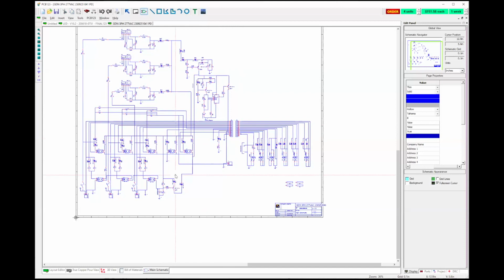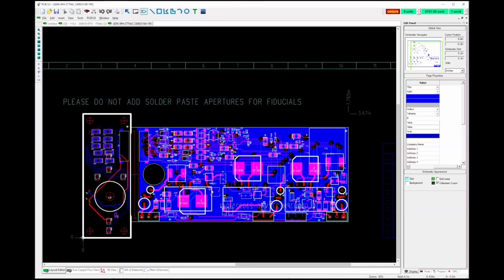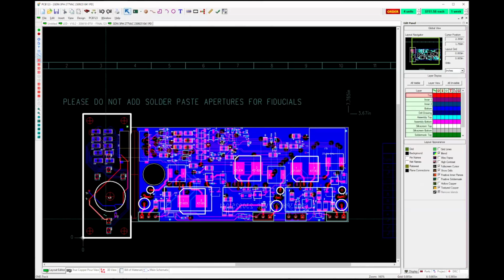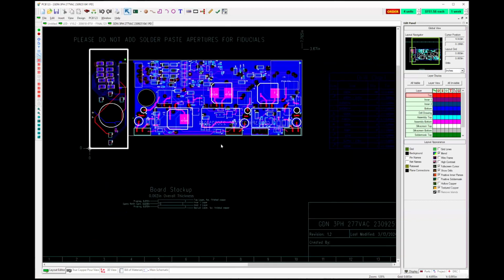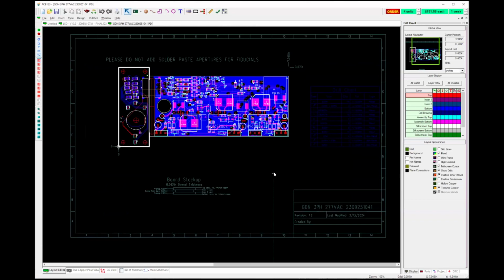After you get your schematic done, of course, you'll go back to your layout editor, and once the schematic's complete, all your parts will land piled up into a stack on the origin. You'll need to move them around and place them on the board logically and per the schematic. And the way I do that is I just take all the parts from this location and spread them out off the board. I zoom out a little bit, and I spread them out, like in this area, so that I can see all the parts that I've got.